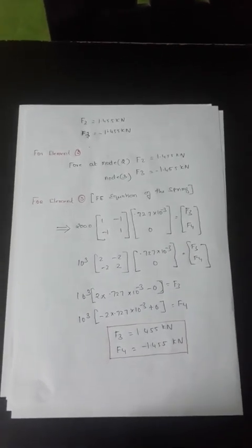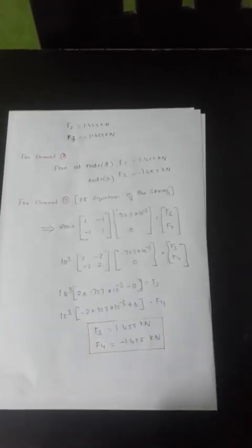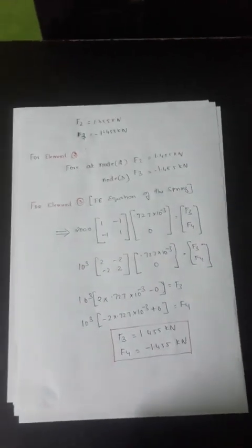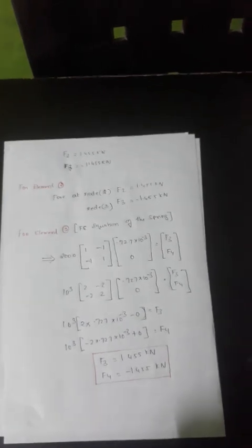First, the self weight is neglected and you find the displacements. Next, you find the nodal forces. The same equation you substitute and you will get 2 equations and 2 unknowns, so the algebraic equations can be solved easily. So don't confuse body forces and nodal forces. Nodal forces are due to the applied force, and the body forces are the gravitational force.